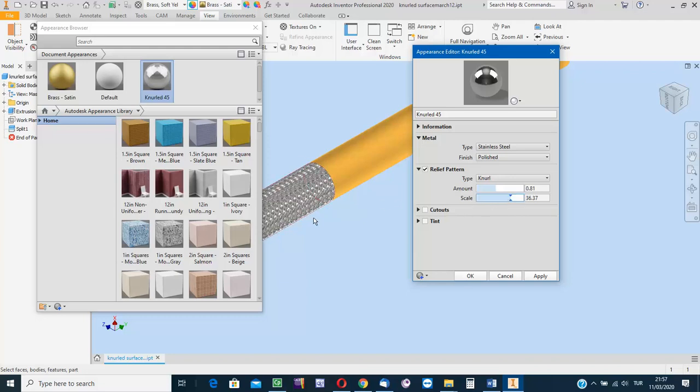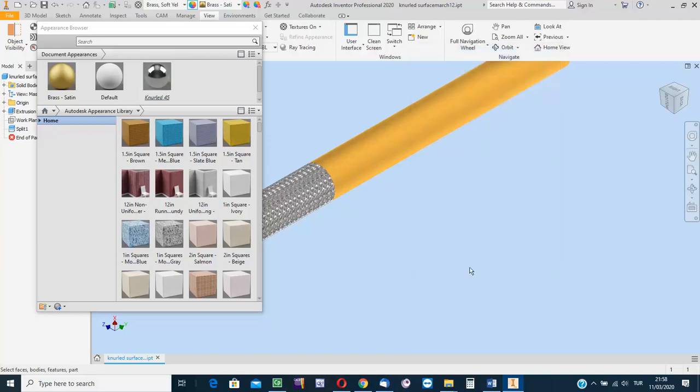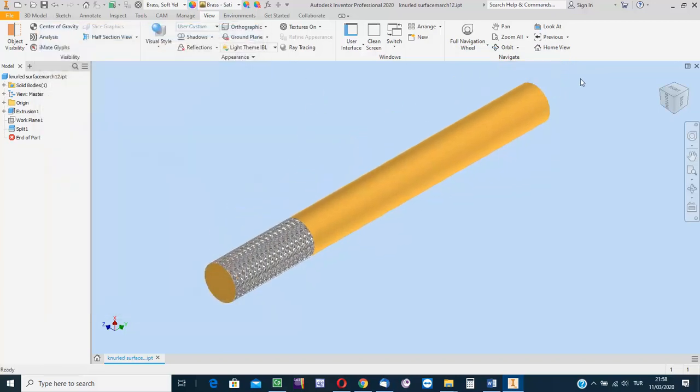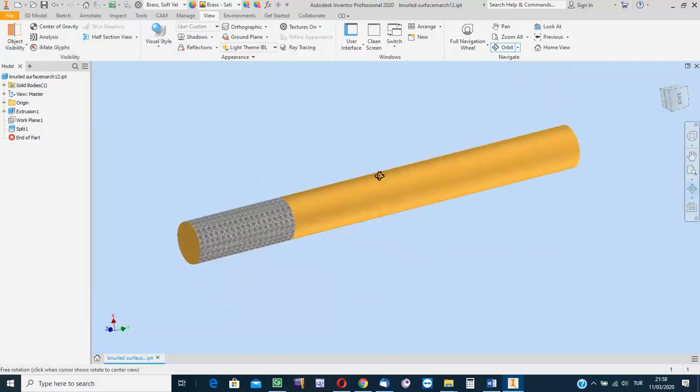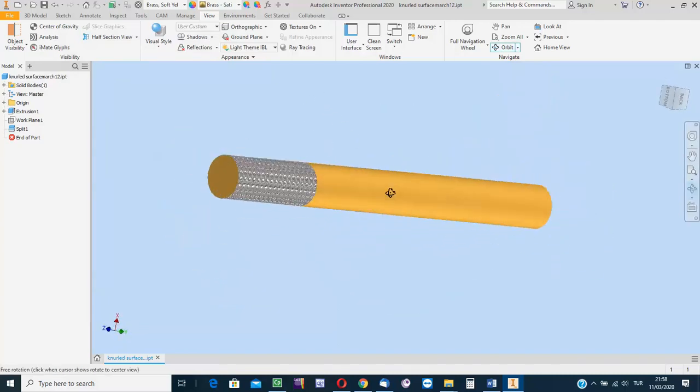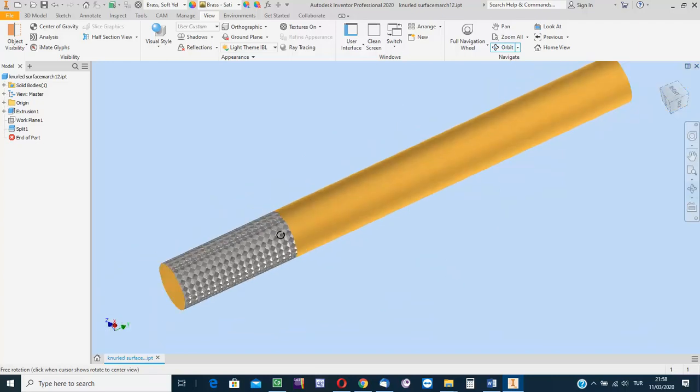It is because it is just an appearance, and if the knurl in the surface effect is distinguishable in a reasonable order, then this means that the position of the scale bar is okay. And then click on Apply and close this dialog box. Yes, in the virtual environment, the solid model environment, this is the thing to do for having such a surface effect.